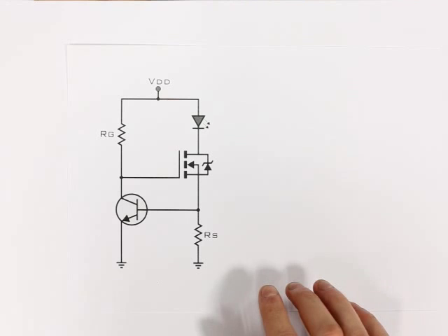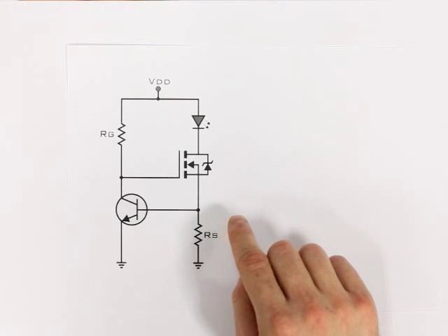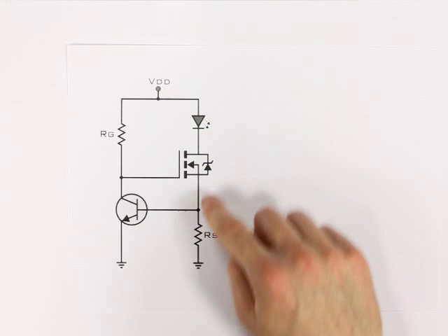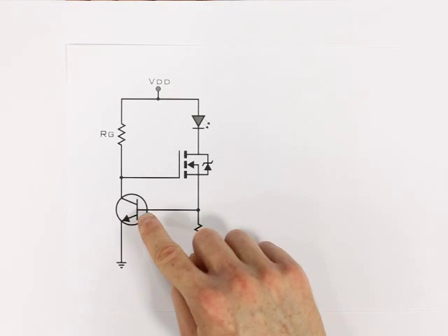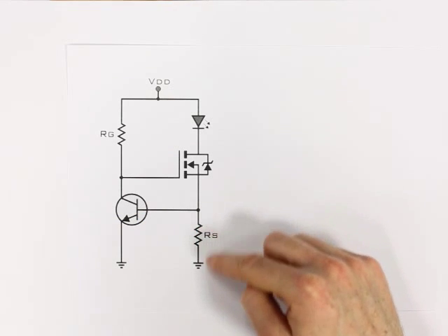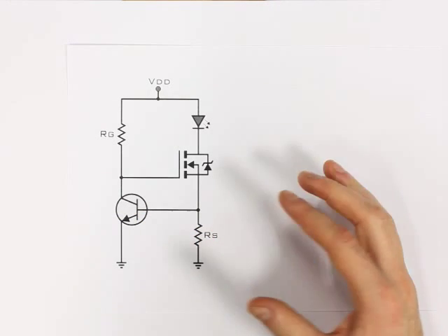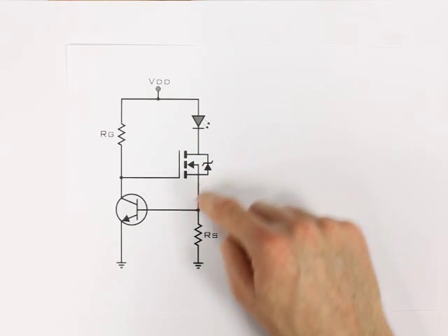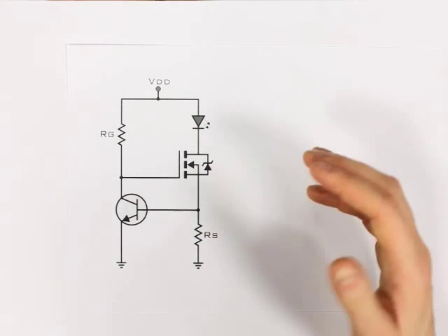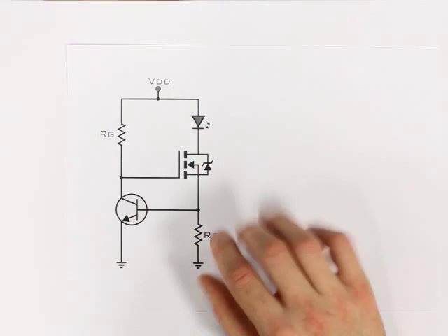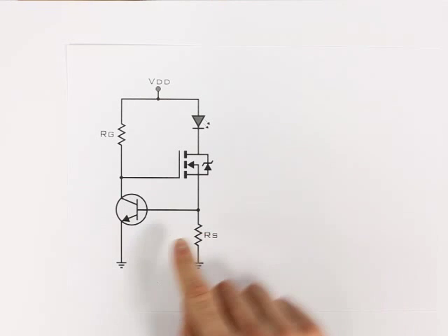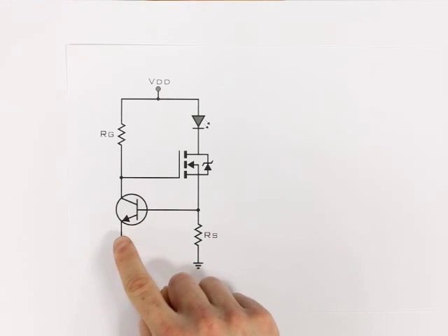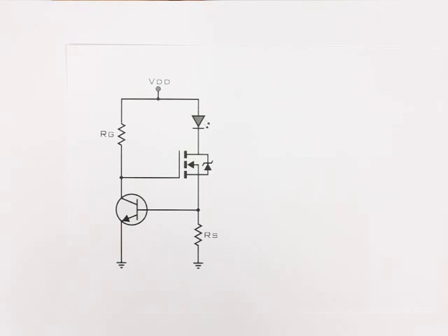There'll be a slight inaccuracy in that, first of all, the current passing into the base of the BJT doesn't actually go through the sense resistor, so it's not included in the calculation, even though it does pass through the LED, but that's going to be absolutely tiny. Probably the bigger variation will be in that the voltage from base to emitter won't be exactly 0.7 volts.